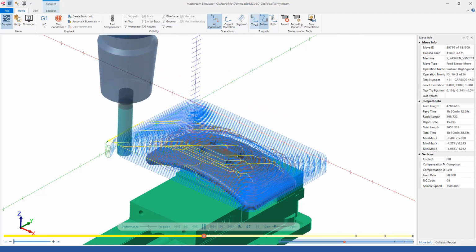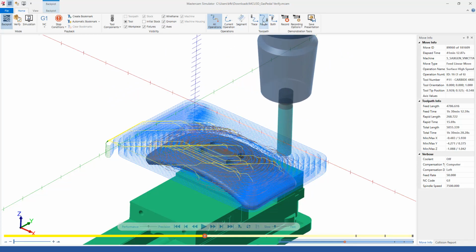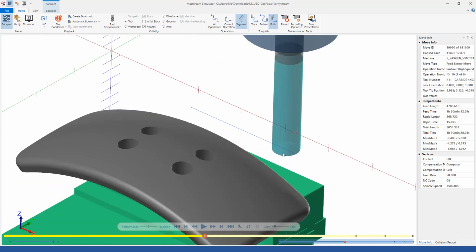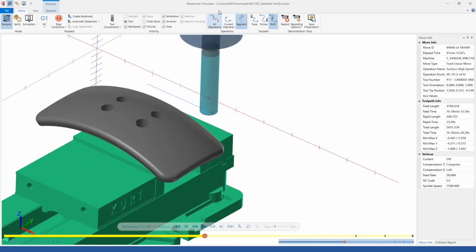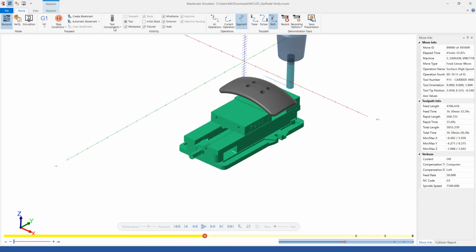You can also do trace, follow, or both. So when we have segment turned on, it's following. If we chose trace as well, or in other words, actually both, so follow and trace, we'll see 10 moves forward and 100 moves back because of the file options we chose here. So that's how the operations and the toolpath works. Let's zoom out here and look at some other options.